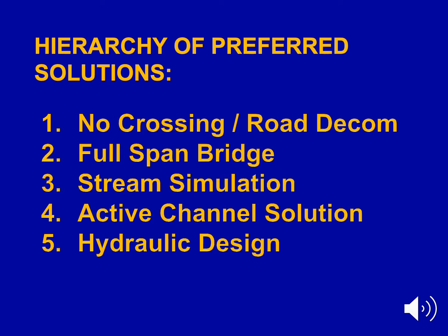Can you take the road out? Really not that applicable to Caltrans' suite of roads, but it is something that comes into play for us for private roads, county roads, forest roads. It is often something that can be looked at. Beyond that, what do we like to see? A full span bridge, floodplain to floodplain. Essentially getting out of the way, let the river do what it needs to do.